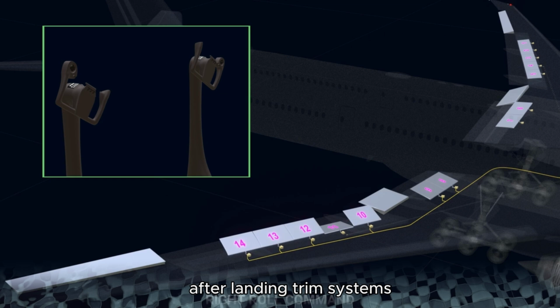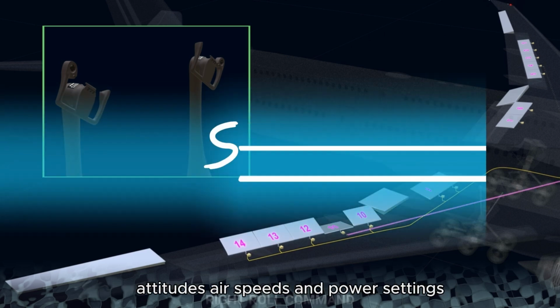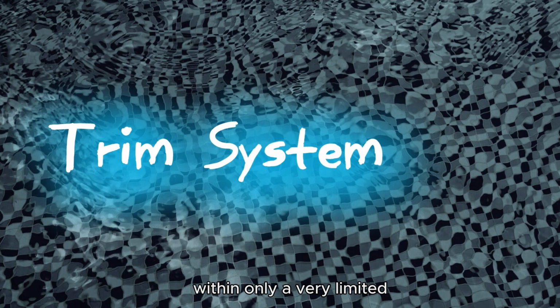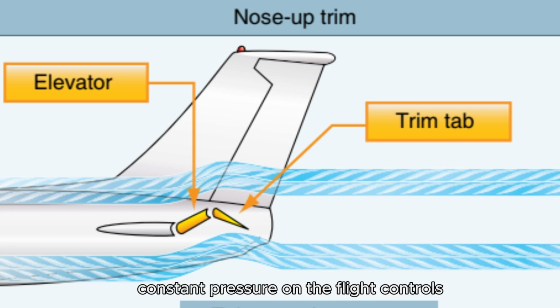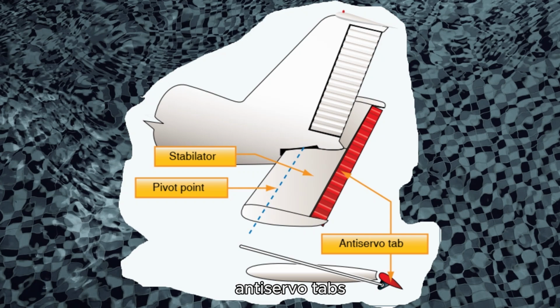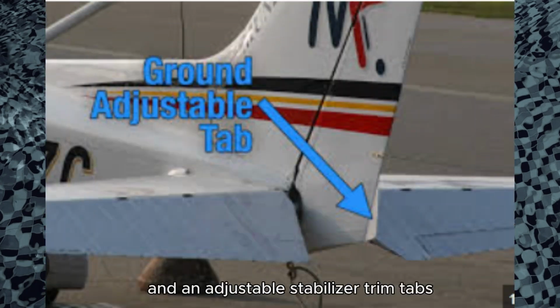Trim systems. Although an aircraft can be operated throughout a wide range of attitudes, airspeeds and power settings, it can be designed to fly hands-off within only a very limited combination of these variables. Trim systems are used to relieve the pilot of the need to maintain constant pressure on the flight controls, designed to help minimize a pilot's workload. Common types of trim systems include trim tabs, balance tabs, anti-servo tabs, ground adjustable tabs, and an adjustable stabilizer.